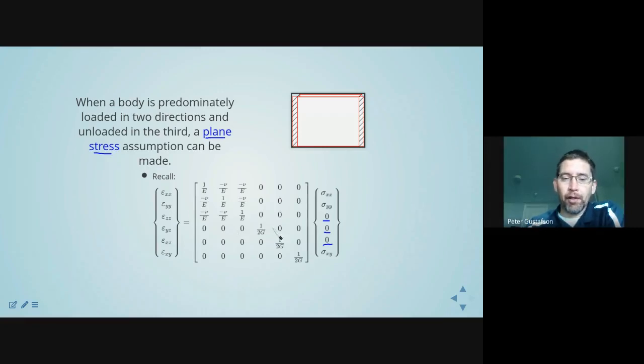Okay, now typically when we have a plane stress scenario, we're going to be generally less interested in the out-of-plane strains. So even though they are not zero, we might not be terribly concerned about what they are, because these are often something like a Poisson strain. And a Poisson strain, when it's unconstrained, is not generally going to cause a failure. So we might not really be terribly interested in what the magnitudes of epsilon zz, yz, and xz are.